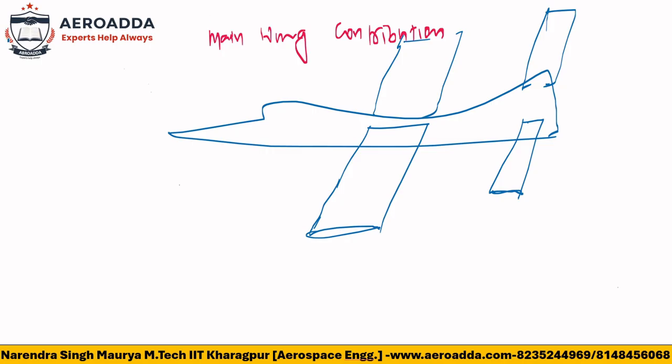Now see, for this aircraft, if you check the lift which is generated by the wing component, here you can say that the drag is nothing but just opposite to the motion of the aircraft. So this is the drag, and the main one is the lift. The lift is generated by the wing here. Obviously you will be talking about lift generation and all at the aerodynamic center, but at the same time here we have the CG. Somewhere here we can say this is the CG. We'll check CG and AC location later on.